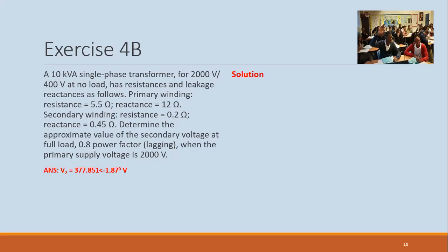They change it just to make sure there are no deposits of, say, carbon in the oil. So yeah, general maintenance would be done on the transformers once a year, especially for those that are usually highly loaded.